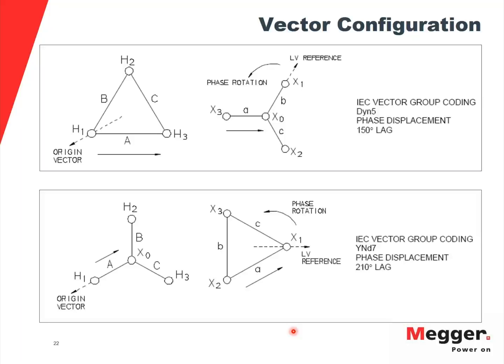So it is very important that you cover not only the winding, but also the bushing terminal, the connection from the winding to the center conductor. You have to take care of those things as well. So my recommendation would be to perform both H1, H0 as well as H1, X1.